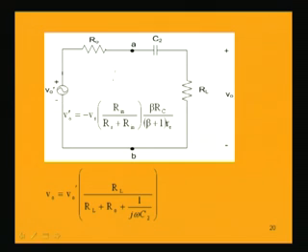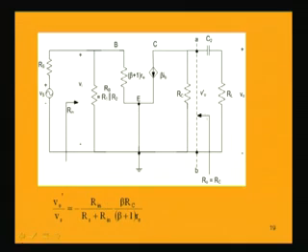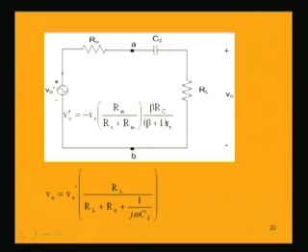It has a resistance R naught in series, that resistance is the output resistance, which is nothing but Rc. So, the whole left side of this circuit from A B has the voltage V naught dash in series with R naught, and the rest of the circuit will be connected there. The rest of the circuit means, to the right of A B we have C2 and RL.